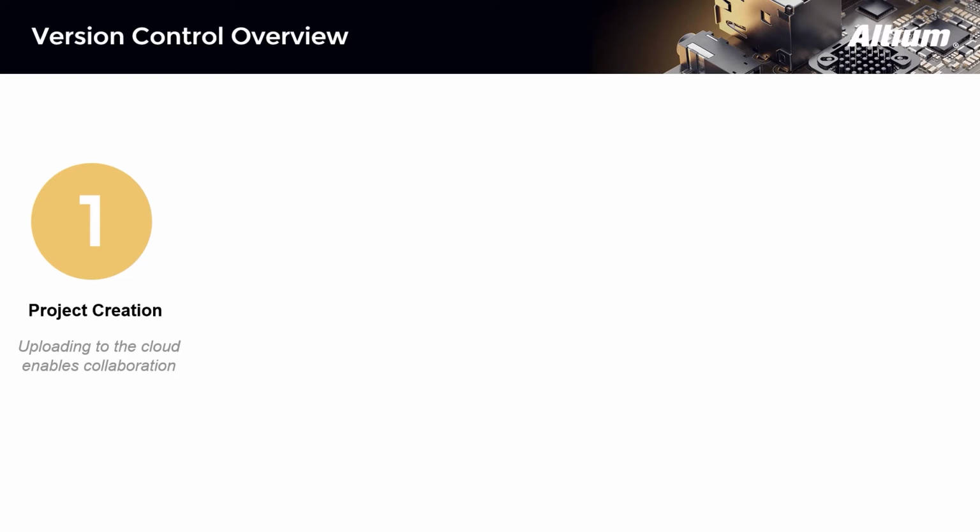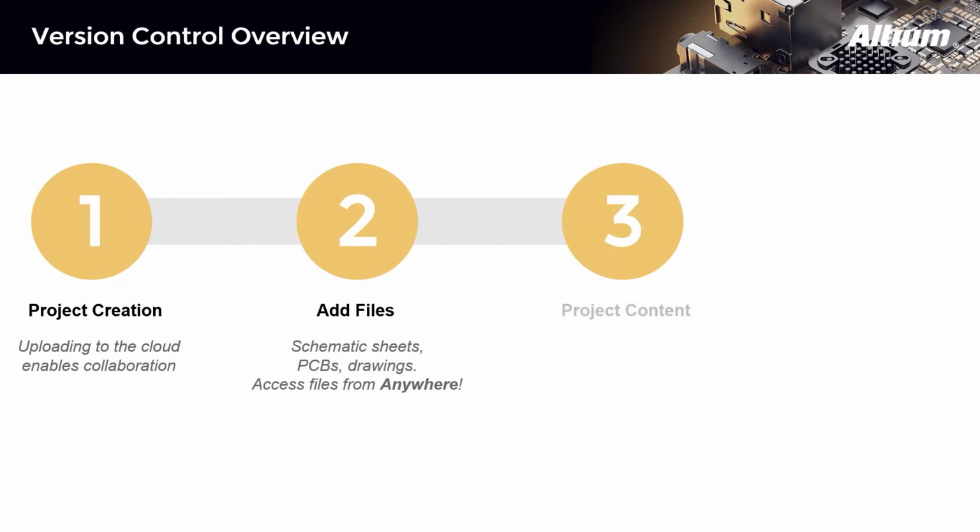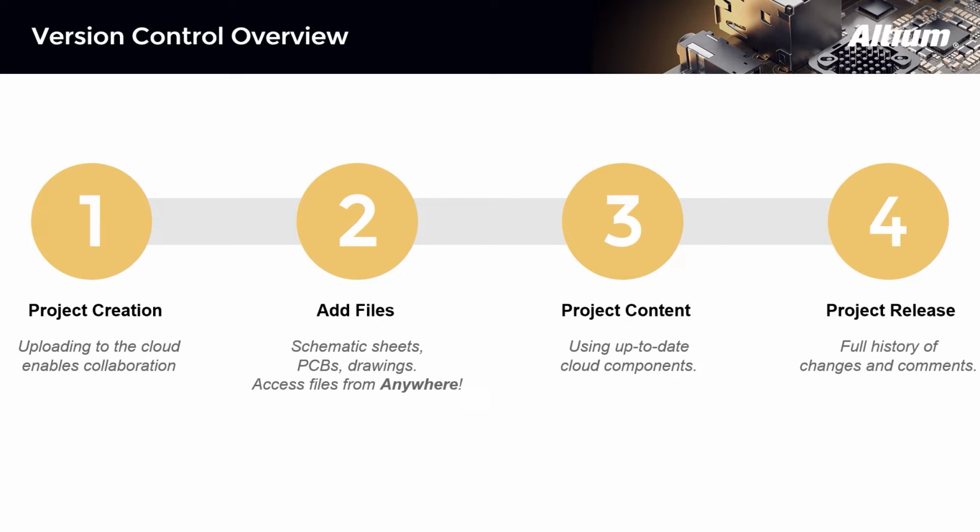Incorporating version control introduces little change to your existing design process. You create a new project as usual, but you select the storage location as your local repository or Altium 365 workspace. By doing so, you create the first project commit. This means you add the project itself with a folder in the version control repository. After that, all changes will be saved.